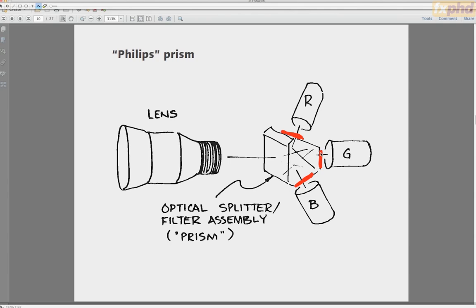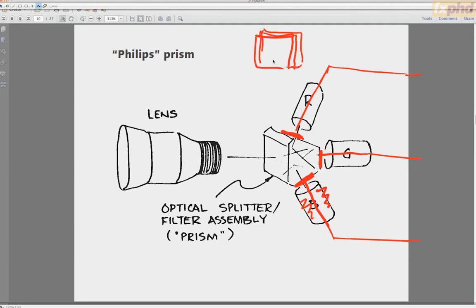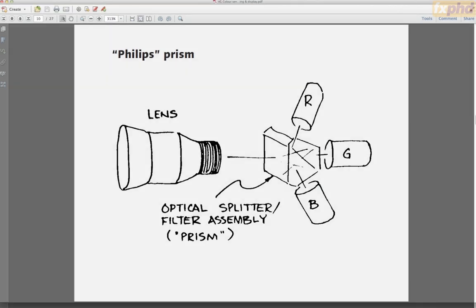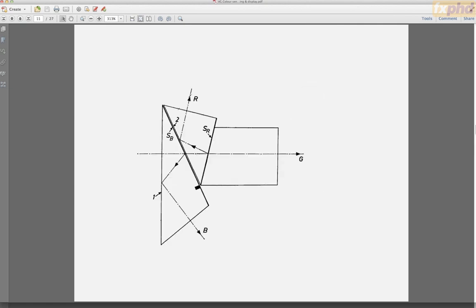And obviously the advantage of a 3-chip camera is you get all 3 signals coming out of the sensors. Well, let's nix the tubes here and just have CCDs. So you've got these 3 signals coming out and they're perfectly in register. And they're basically optically superimposed. So there's no need for any kind of demosaicing, any of that. So that's the use of dichroic filters at capture time, and you can also use dichroic filters to display, and that's what a DLP cinema class projector does.